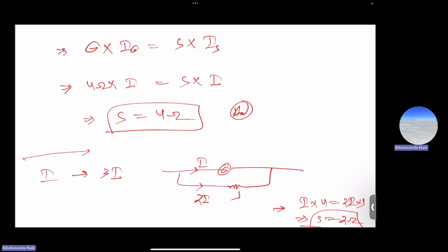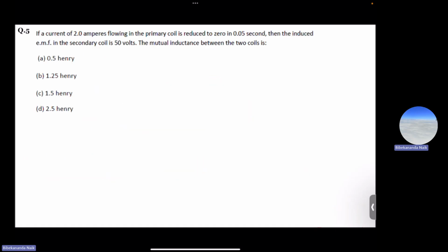The larger the current range you require, the lesser the resistance that will be connected in parallel, because the lesser the resistance, the more current will flow through that branch, so that the current flowing through the galvanometer remains the same. And this is the way to change the range of the galvanometer, the range of the ammeter. I hope this is clear to everyone.